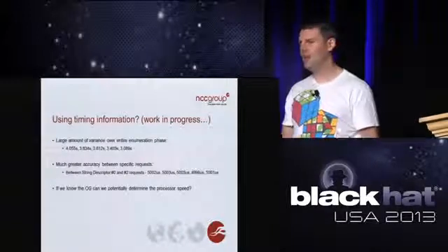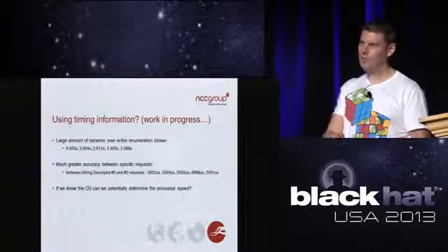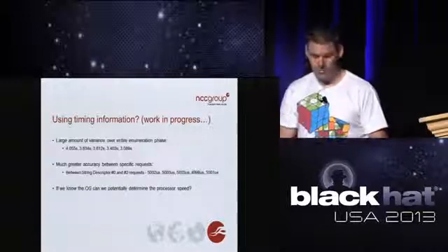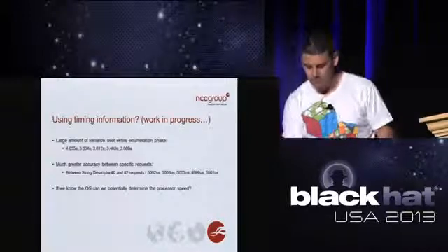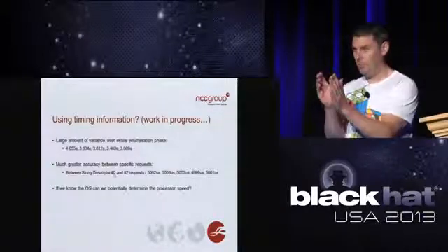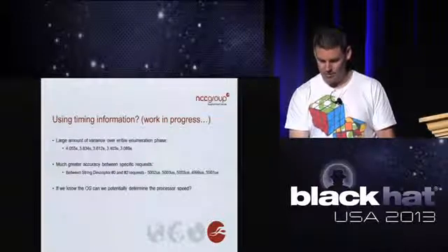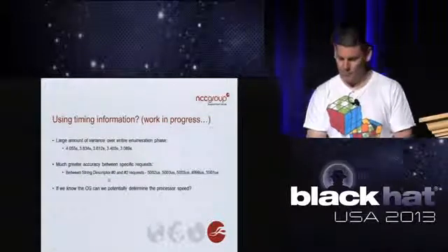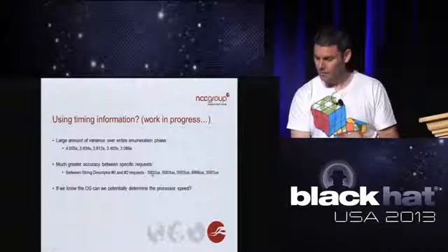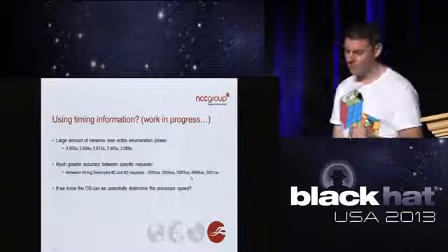It typically takes around 5 or 6 seconds to go from initial device insertion to the point where class-specific communications occur. But if you tie it down to the timing between specific elements within that enumeration phase, here I've looked at the difference between the timing of the request for string descriptor 0 and string descriptor 2, you're talking of a difference of 1 or 2 microseconds.